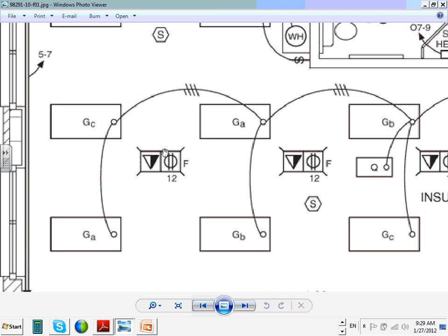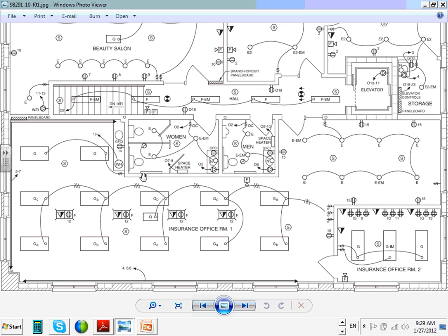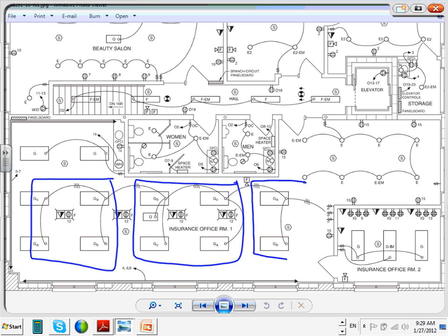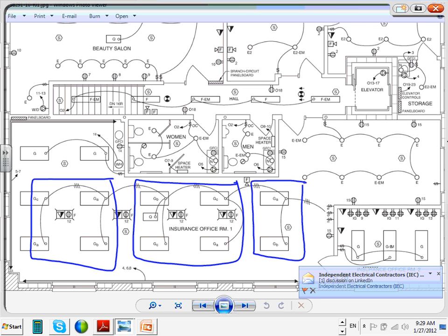You can do that. Dustin, what I told you, the poor man's job is to grab a chunk of them, one row, and put it on A. You could do it in multiple ways. One way that you can do it, which might be cheaper, is to put this one on switch A, this one on switch B, and this one on switch C, right? What they decided to do is they want 3 levels of lighting everywhere. Can you guys see how switching decides how you want to use the building? This is an open office here. People are sitting there all the time.